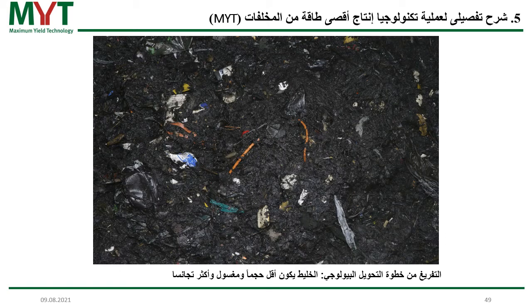On the next slide, you see how this slurry looks after 2 to 3 days of mixing. It's reduced in size, so we do not need a shredder to reduce the size. A shredder actually requires a lot of electricity and it's expensive in operation. With this mixing, you reduce it automatically because the material is just pushed towards each other. It's also washed, and the waste is much more homogenized than before, so the slurry looks quite even all over.